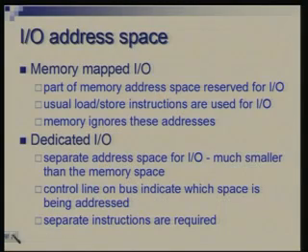In the second approach, you have to have a different address space for input output, and it need not be as large as what you have for memory. It is much smaller. You could have, let us say, 10 to 15 bits trying to address the I/O devices. So, it need not be a very large address space,